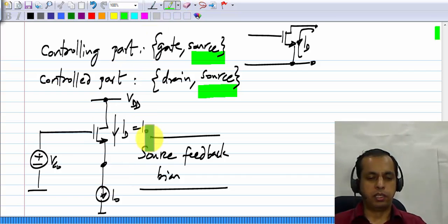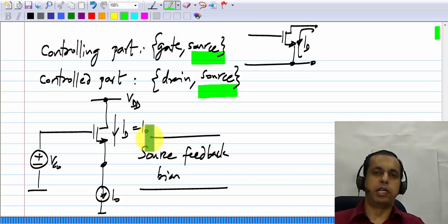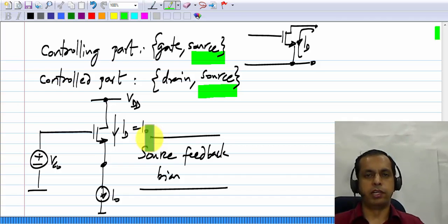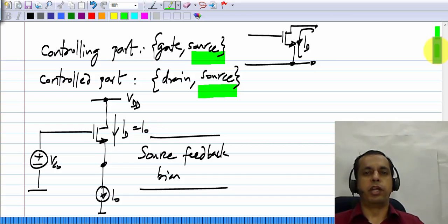And in the subsequent lessons we will look at how to realize amplifiers using this type of bias. Like I've said many times before, you can have many different kinds of bias circuits and many different kinds of functions. That is the incremental picture that we want to realize. Right now we know only one of them, that's the common source amplifier, but typically any function can be realized with any bias circuit. It's possible. Now of course some of them are more convenient than others, so they will be preferred, but you can have a variety of functions, a variety of bias circuits, and a combination of biasing and the realization of the functionality. So this is why there is a huge variety in circuits.